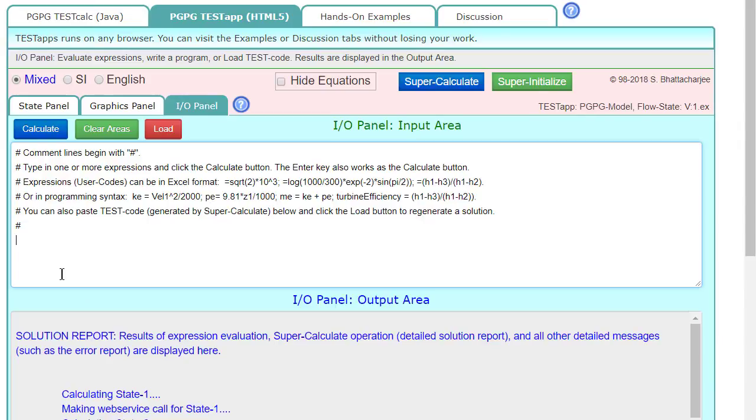Right, and then for s.gen, we're assuming it's steady state, and we're assuming that it is adiabatic because it didn't mention anything about heat transfer. So using the energy equation, we can derive that s.gen is going to just be the difference in m dot times specific entropy.